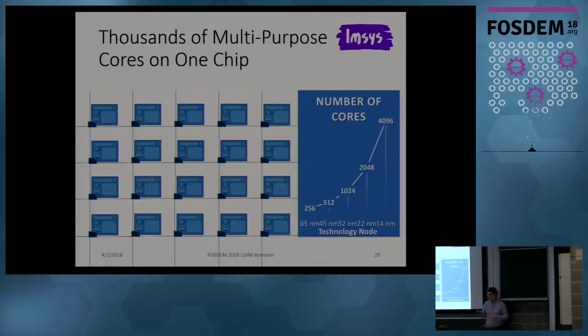But about keeping everything in microcode and not moving into hardware, as I mentioned, our processor core is quite small compared to the mainstream ones. We have 65 nanometer, which we use now, and we don't have a really massively multi-core solution yet. But it's theoretically possible to have several thousands of cores on state-of-the-art processing nodes.